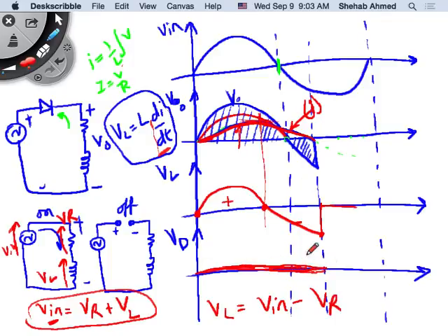And then what? Hint hint. Exactly, right here, it's open circuit, guys. This is an open circuit, so there's no current flowing. So this terminal is basically this voltage, and this terminal is basically this voltage. So you draw your input voltage maybe dotted like that, and this will be the diode voltage, the voltage across the diode. Okay?